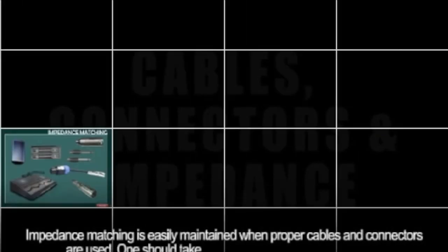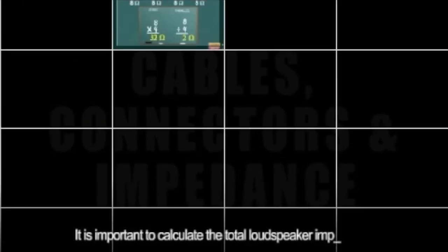Impedance matching is easily maintained when proper cables and connectors are used. One should take caution when multiple adapters are used to make a connection. It is important to calculate the total loudspeaker impedance load before energizing a power amplifier.